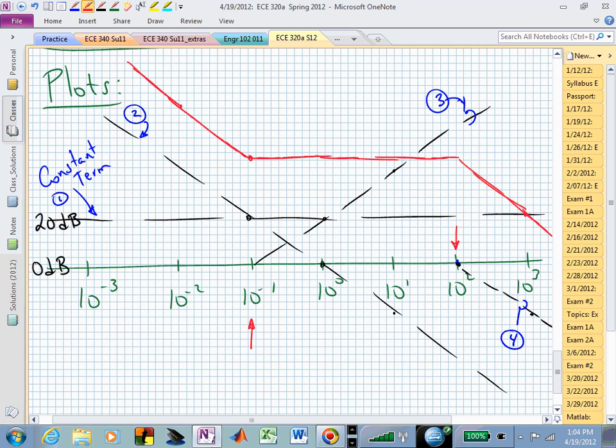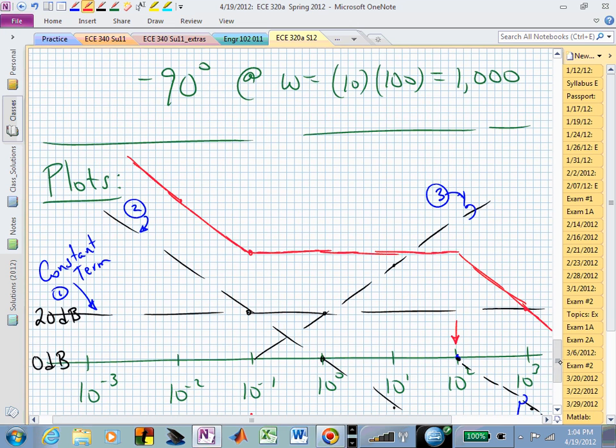So you're going to see 200 cosine of 1t plus, that's why we need to plot the phase. So this is the magnitude plot, but once we have the phase plot, you can find the sinusoidal steady state for any frequency that somebody gives you. You don't have to do it point for point in the S-plane. Is that making sense? And that's why these are basically insightful diagrams, because it tells you a lot.